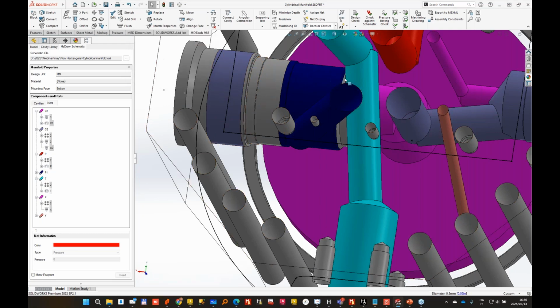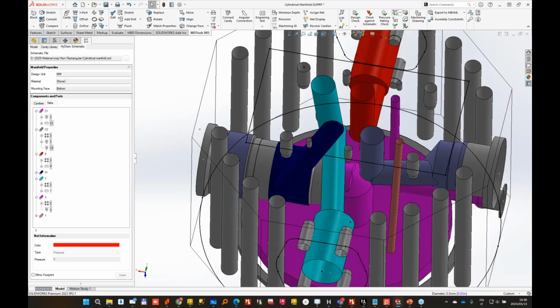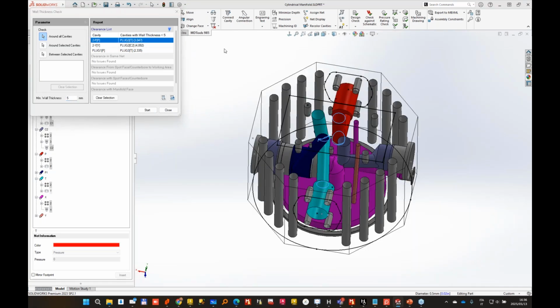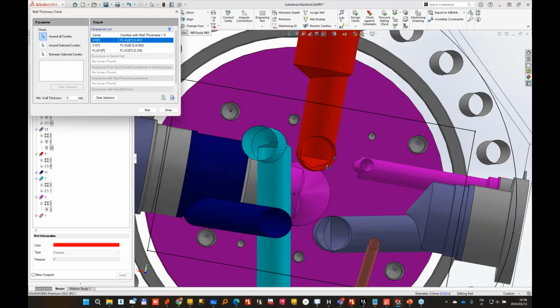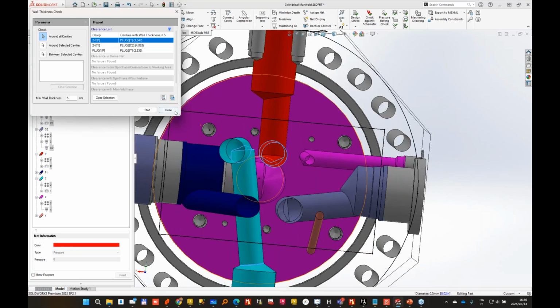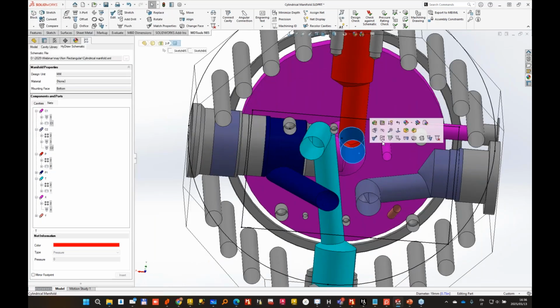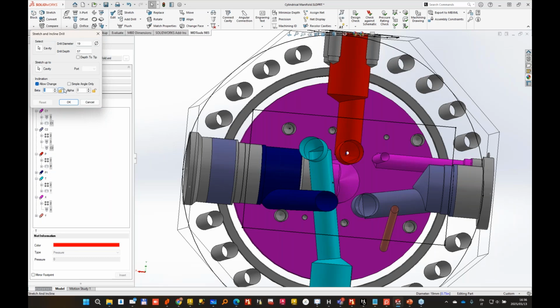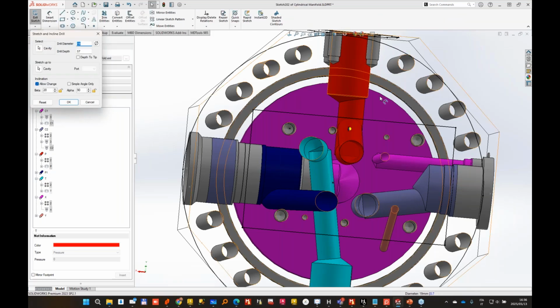Or if we have doubt, we have the possibility to run the wall thickness around all cavities. I can see one other issue here, which is this one. Here we have only 3 millimeter between these drills. In this case, if I had to machine this block, the manufacturer will not be very happy, but now I need to do another inclination. So for those